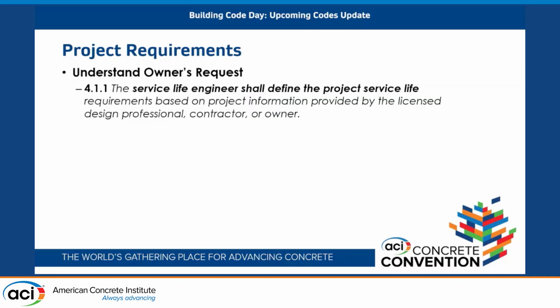In my professional experience, one of the biggest pitfalls of service life prediction is that owners have a structure, and after several years they start to see problems, and they look at it and say, well, this was built 10, 15, or 20 years ago. What's going on? The fact is that they never planned for something that would last more than that under those specific conditions. Parking garages are a good example because they're built everywhere in the country, and the exposure conditions in Florida are going to be different than in Minnesota. If you're a company that manages this type of property, you're not going to have a good understanding of why these parking garages, even if they look similar, are not behaving the same way.